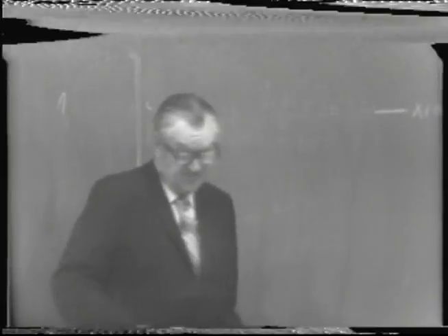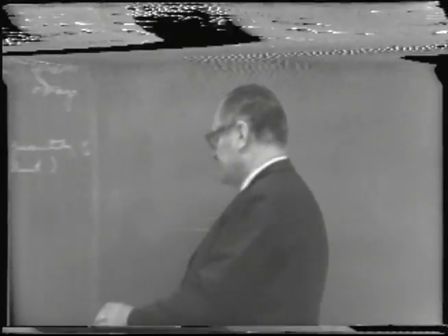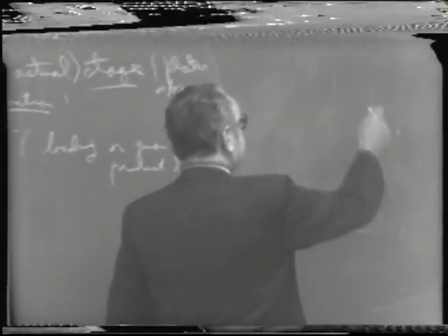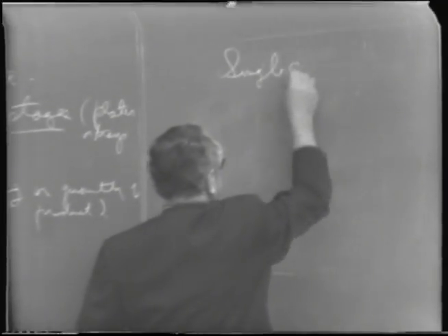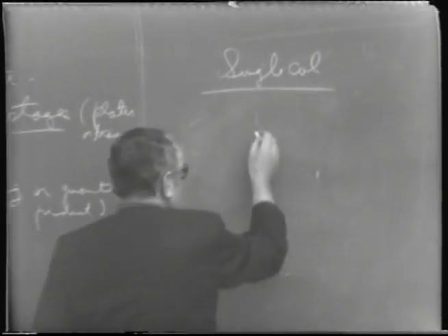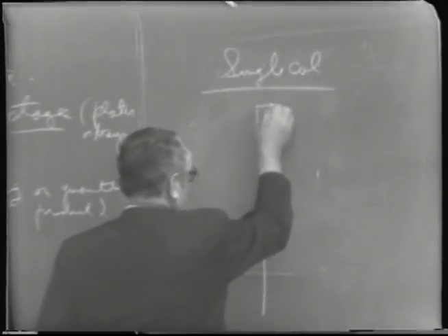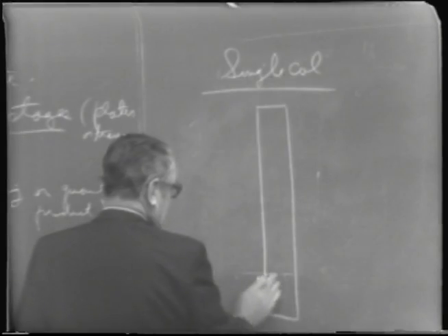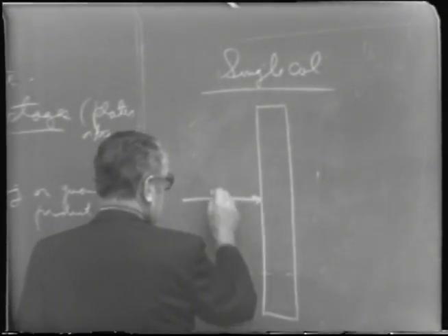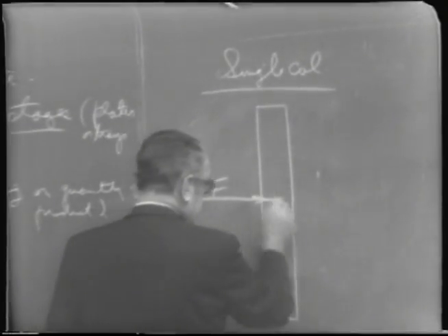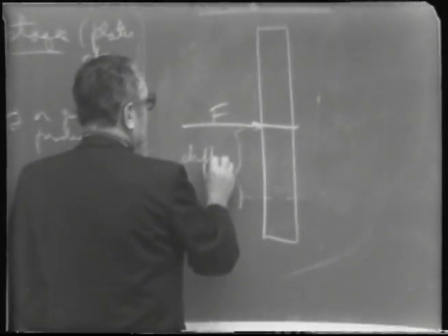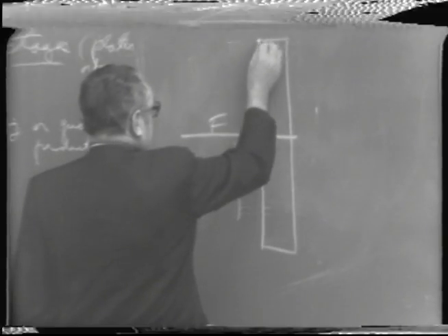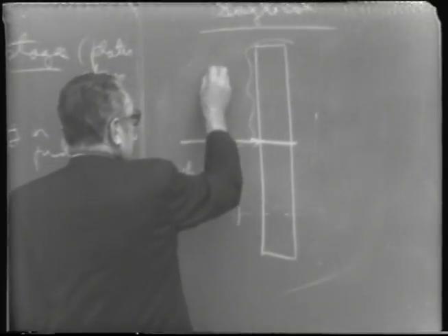And they also have to make provisions for pumping the liquid overflow from the bottom of the concentrating section back to the stripping section. In other words, a single column in its simple form would be something like this, where the feed goes in here, and we call this a stripping section. And the upper part here, the concentrating section.